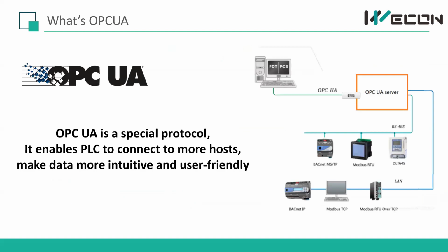The OPCUA protocol enables our PLC to connect to more hosts. Before, if our PLC connected with a SCADA that didn't support our Wecon protocol, you maybe needed to use Modbus, and the Modbus address is not very user friendly.